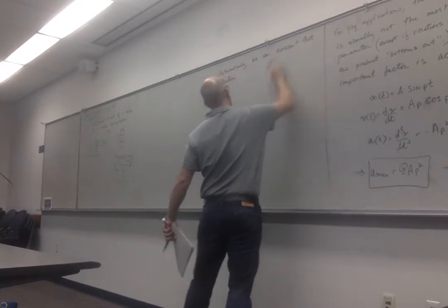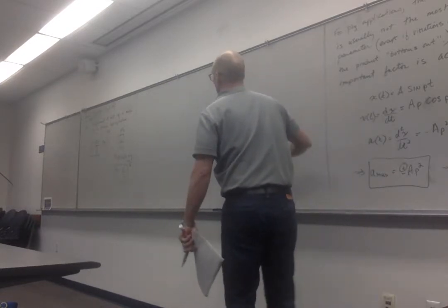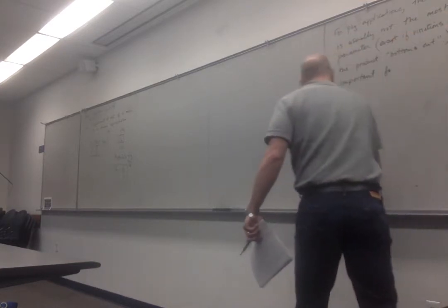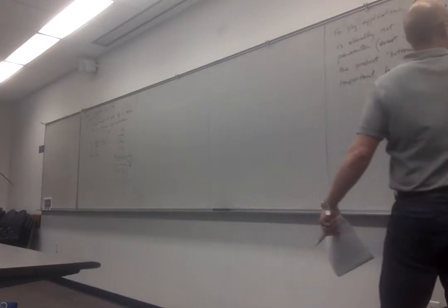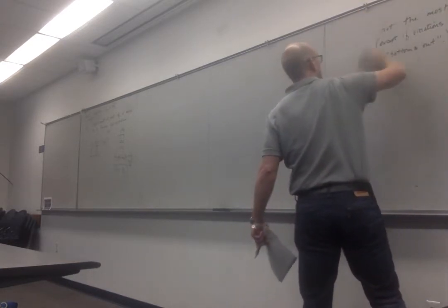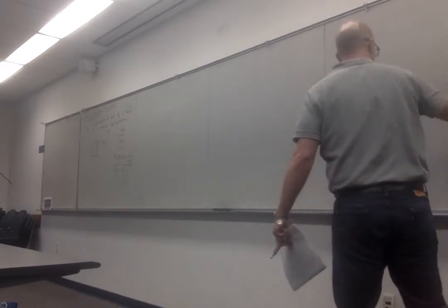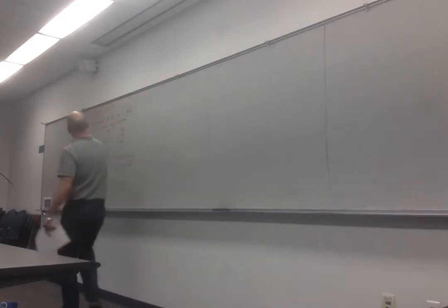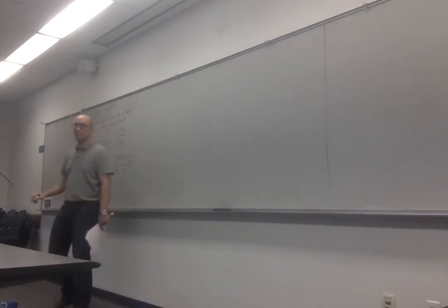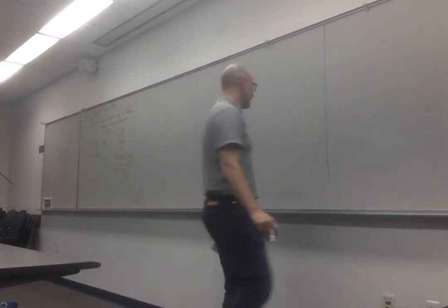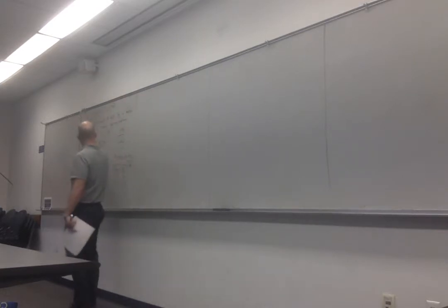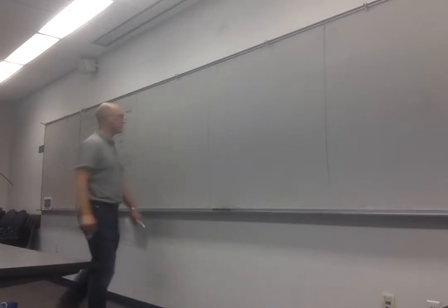And sometimes when we start doing analysis of motion during vibration and so on, we'll have to remember about that static deflection, because when we analyze the force of the spring, we need to realize that once the mass has been placed on it, there's basically a new equilibrium. At equilibrium, meaning if it's sitting there, there's a force associated with that spring. Okay, it is pushing the mass upwards according to its weight. Only where the spring is at its natural equilibrium position, there's 0 force here.